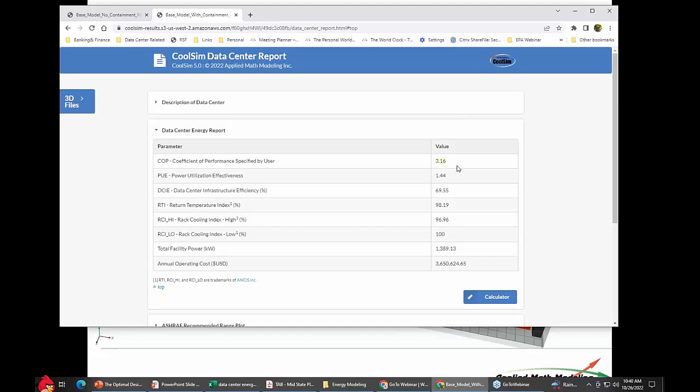Now, there are many of you who say, well, that's pretty rough. Yeah, Henry's probably having a fit because there's a lot in that right there. I made some pretty big assumptions there. But even if you model a data center distinctly, uniquely, discretely, you're going to end up with an average COP for a calendar year. Remember, these things are not steady state anyway. The COP is going to vary by the hour, depending upon, for example, if you've got an outside economizer, on outside air temp. It depends on a lot of things. Depends on the cost of electricity as well, by the way.